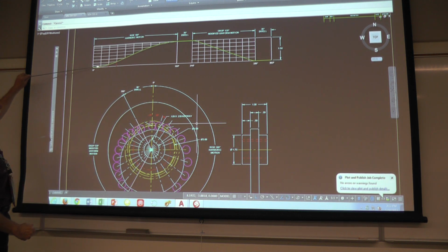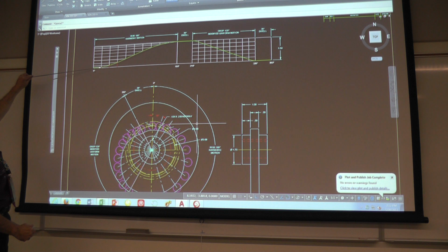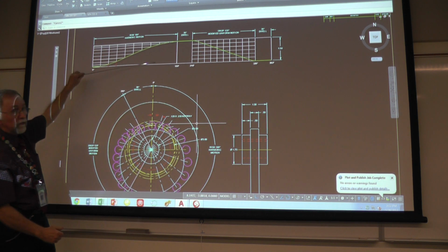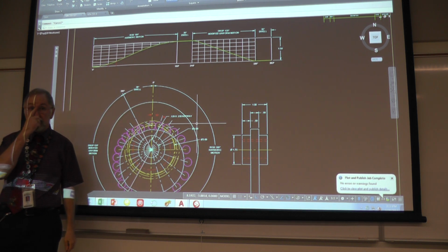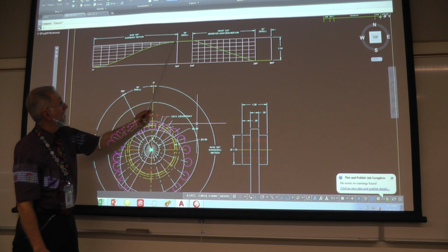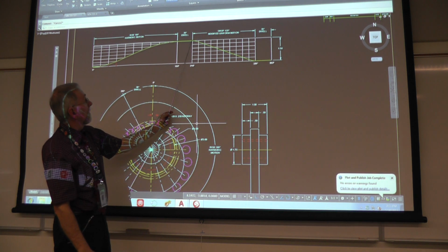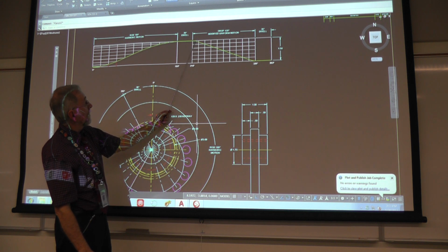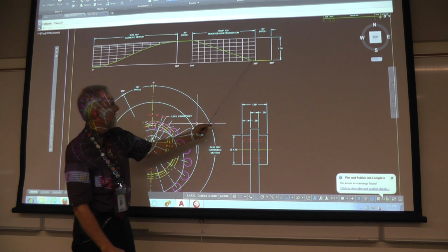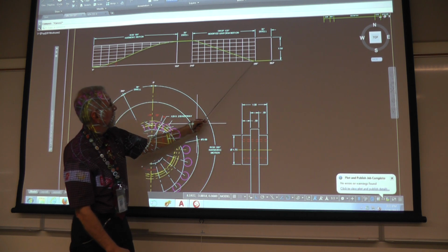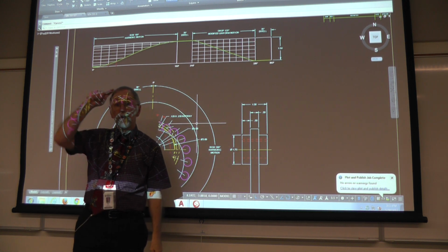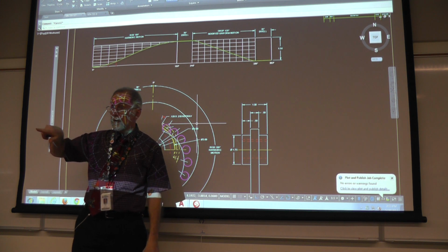And then as you put a spline line in here, again, you hit the little intersection points. I took out these bottom ones to just kind of clean it up and make it look a little easier to figure out. So again, you're just making the spline. This is a line element. You could draw a circle in here that has a radius of 0.75 and a circle down here, and then draw a line that's tangent to the edges of the circle and then trim the circle out. So you get that little curve, line, curve, and it's all tangent.